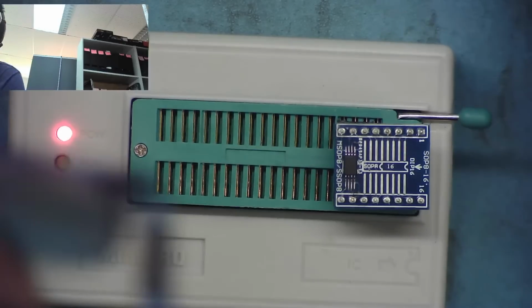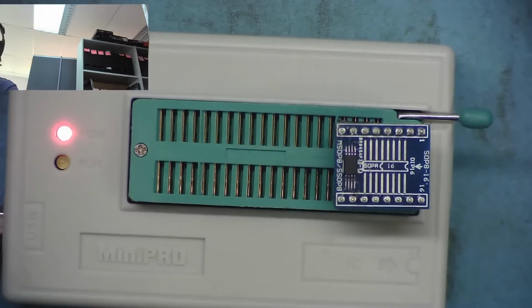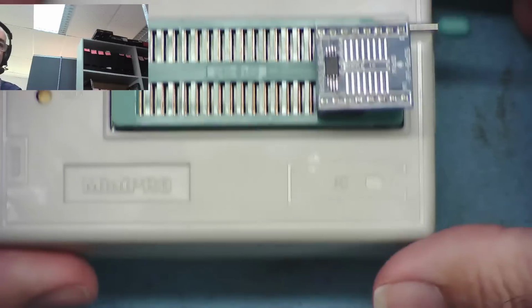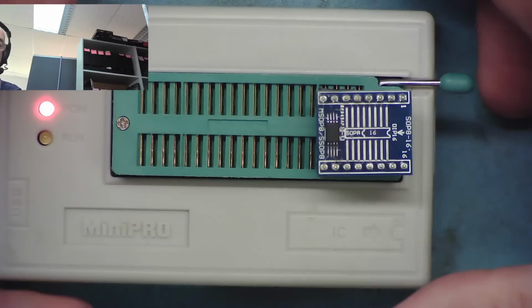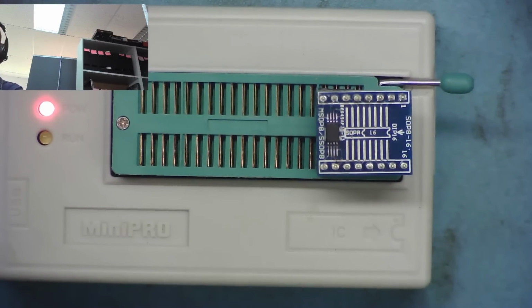Hi guys, I thought I'd have another look at this laptop screen. I was messing with this last week, trying to get it to work, and basically everything seemed to be okay. All the voltages were there, sending data to the screen. So I swapped the video chip, I swapped the EPROMs, and it didn't make any difference. And at this point I thought, as I said on the video, I can't really see any difference between these two. It should work.